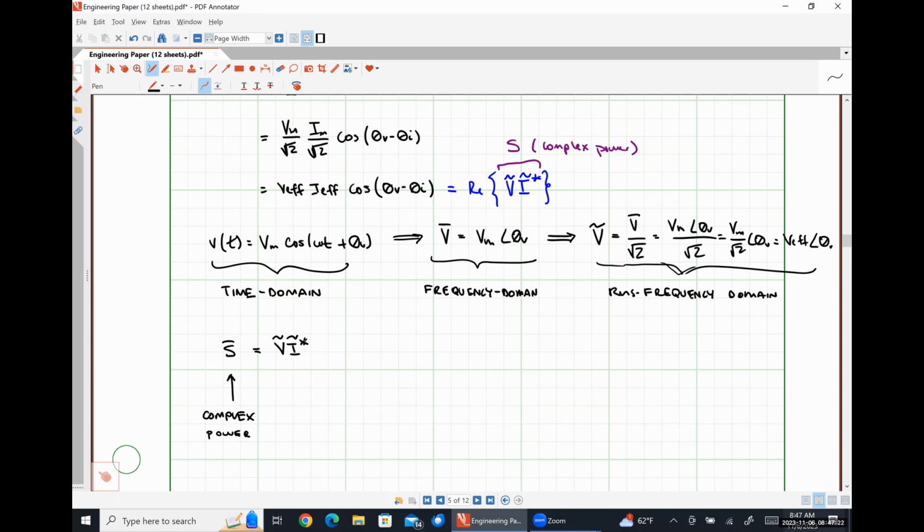By the way, the only reason we are using a complex conjugate here is because we're trying to force a negative sign, because that's what our average power relationship has, theta V minus theta I. If it were theta V plus theta I, we wouldn't need that conjugate operation, but unfortunately it is. All right, so this is a trick question. What are the units for complex power?